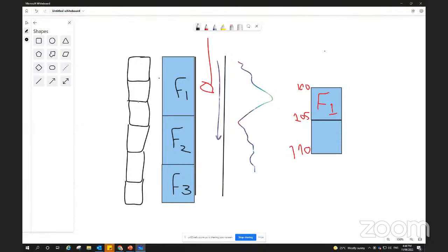It will measure the thickness, then come to this cell and fill it with F1. The second cell is still adjacent to the raw data of facies F1, so it gives F1. After that, in this cell, the software sees that there's a boundary between facies 1 and facies 2.